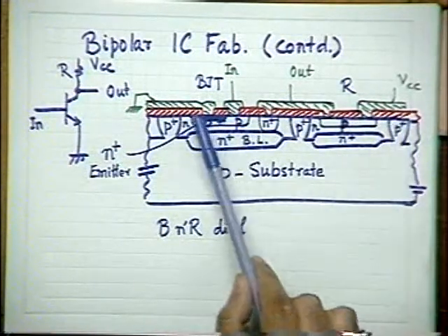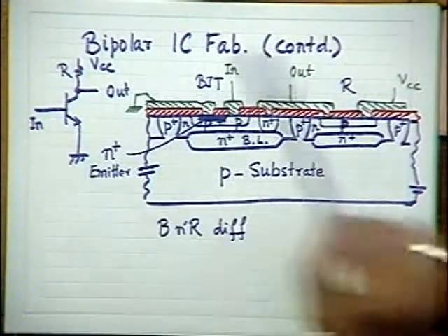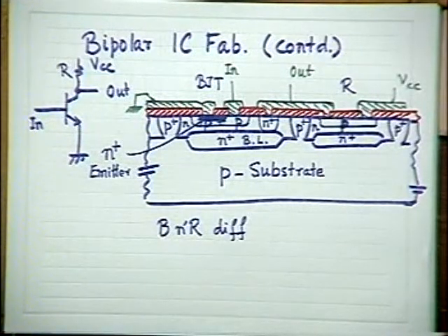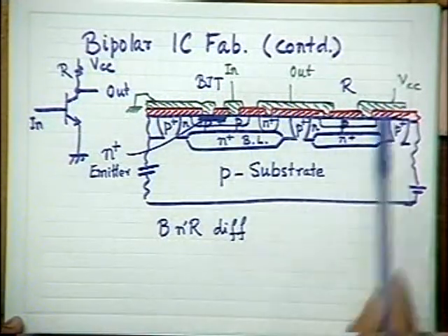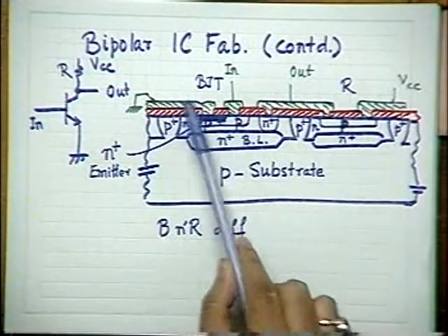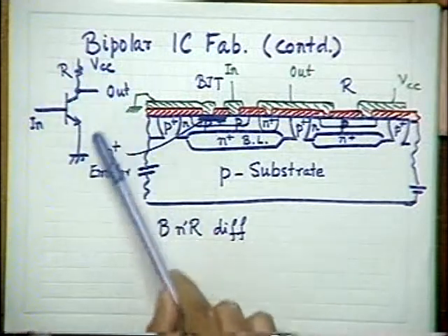Thereafter, after the contact hole formation, you please compare with the earlier steps. We metallize it. Everywhere you deposit a metal film. And using the last but one mask, we pattern the metal. The green one is the metal here. The green level is the metal. We pattern it to form the circuit, this particular layout.